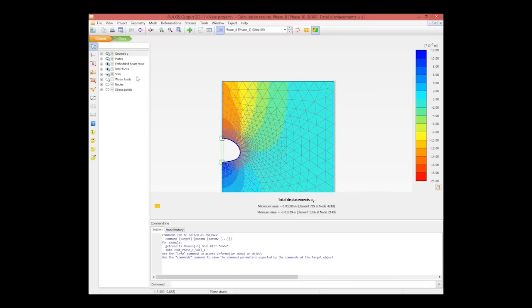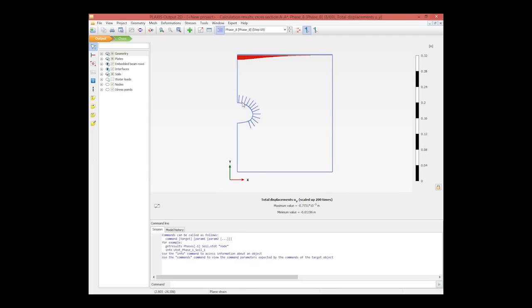We can also draw a cross-section and evaluate the profile of the settlement at the top. And we can also then start moving it up and down to also evaluate it at different locations, like this, all the way to the side, and eventually at the bottom when we start to see soil heave, actually. And as we further go down, then the heave starts diminishing until it fully vanishes.